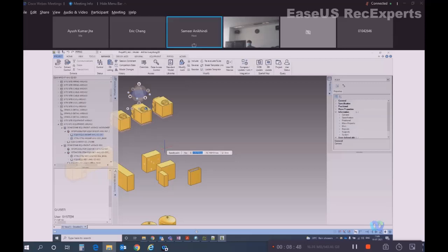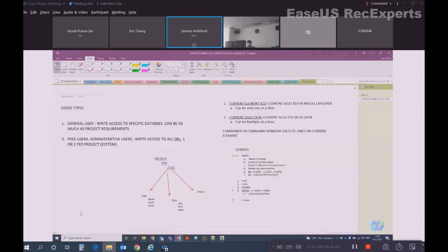If you press tilt key, right, this is a distance, angle and elevation. So you can see if I press it again, it changes to cylindrical coordinate. So there are three kinds of coordinate you can work with. I will write it here.